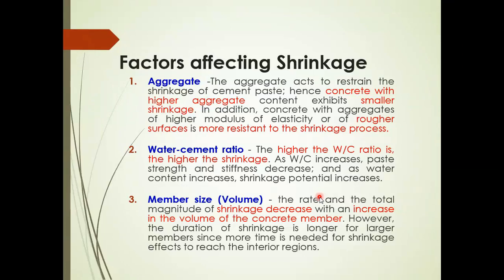The second one is the water-cement ratio. A higher water-cement ratio will lead to higher shrinkage. So as the water-cement ratio increases, the paste strength and stiffness decrease, and as the water content increases, the shrinkage will increase.